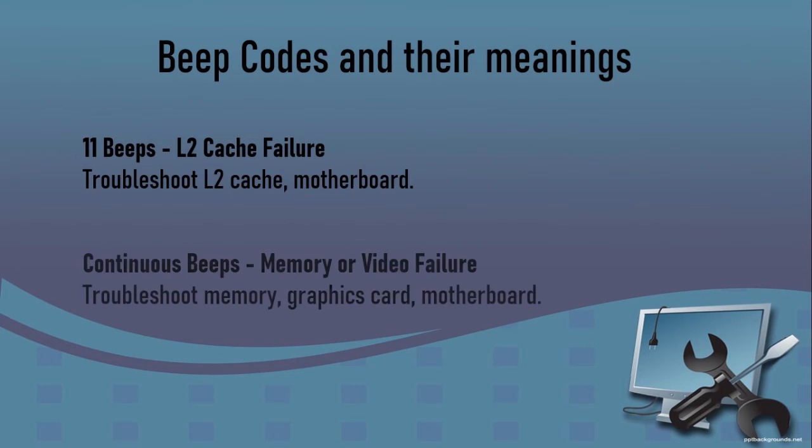And lastly, continuous beeps: memory or video failure. Troubleshoot memory, graphics card, and motherboard. This kind of beeping does not have a pattern or number of beeps. Kumbaga, dire-diretso lang. So it is recommended to troubleshoot the motherboard, especially the expansion cards and the memory slots.